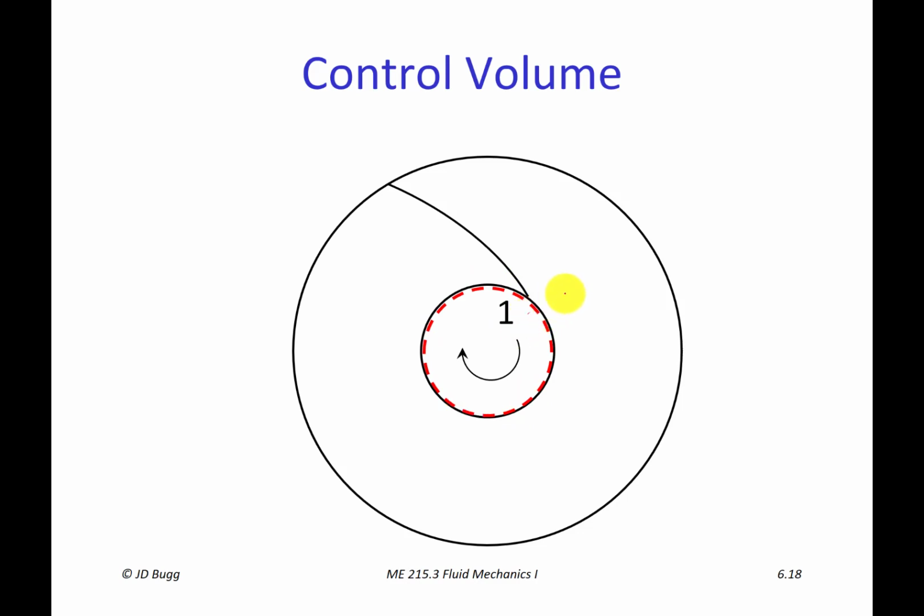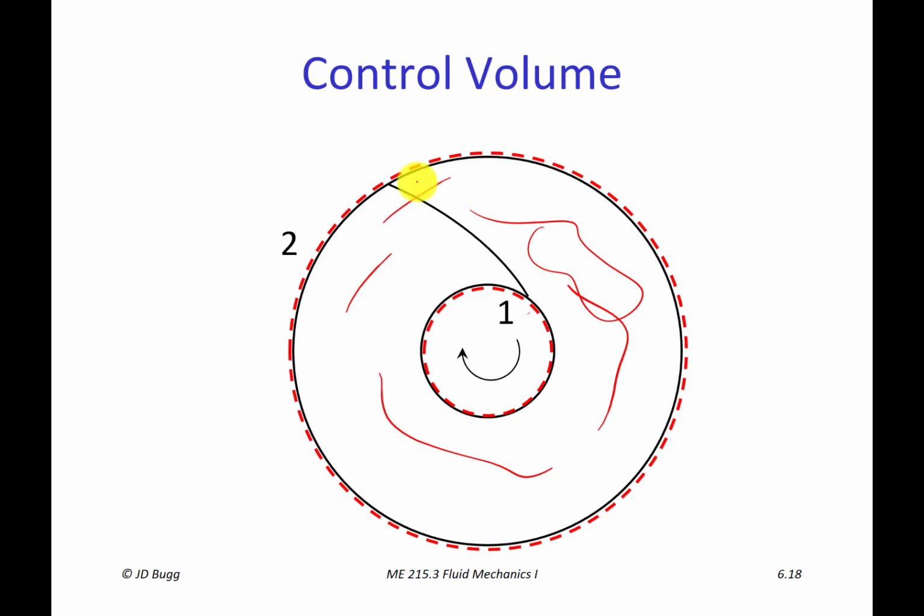So it comes into our control volume, then it interacts with the blades that are in here. We're going to talk lots about that, but eventually it leaves our control volume, and the exit of the control volume is out there. So again, this is a cylindrical surface. We're just seeing it in cross section here. It protrudes in or out of the screen a little bit, and again, the thickness of the impeller out there typically would be different than the thickness of the impeller here, but that's another parameter that we'll see show up in the analysis. So both this inlet surface, which I've labeled 1, and the exit surface, which I've labeled 2, are cylindrical surfaces. So that defines our control volume.